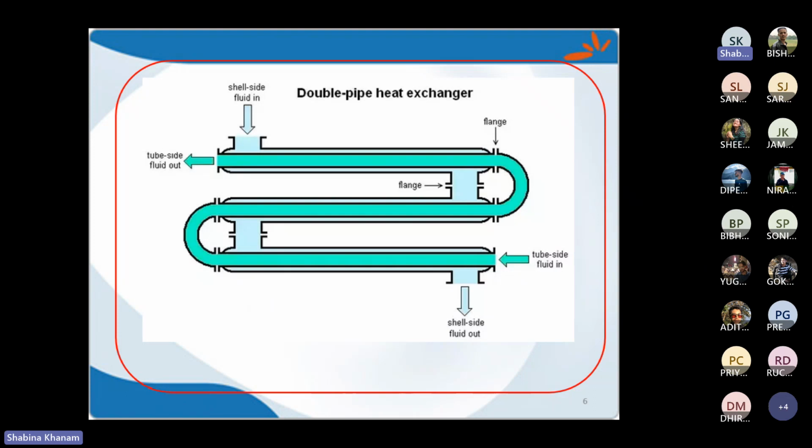The reason could be that bending of two concentric pipes is very difficult. In that way, the inner area will not be uniform throughout, especially in the bending case, but that will be very easy to maintain in a straight case. So bending will be done only with the inner pipe, but wherever the heat transfer is done, there we will have two different pipes of different diameter.